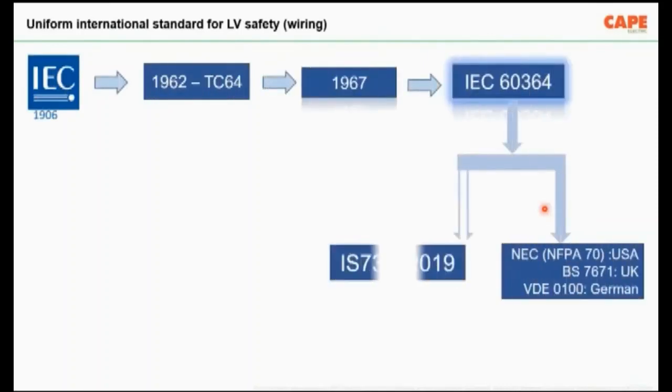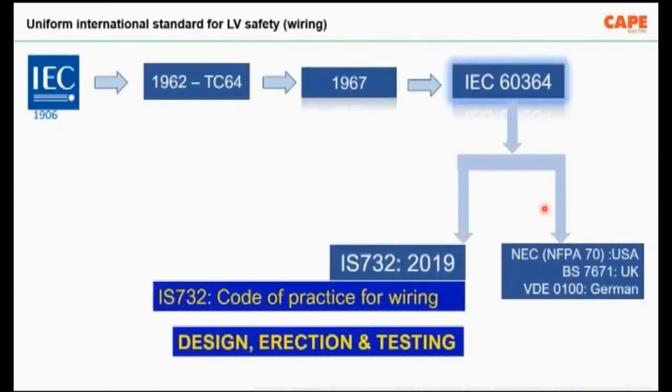Now, what I am trying to explain to you is, if you look at any of the international standards on EMI and EMC, the foreign standards like American or British standards, what they say is the basic electrical system shall satisfy the national wiring rule. That is regarding safety. For example, if we look at the American standards, they always say the electrical system must be as per NEC or NFPA 70, both are the same. So over and above this, the other additional safety features are built.